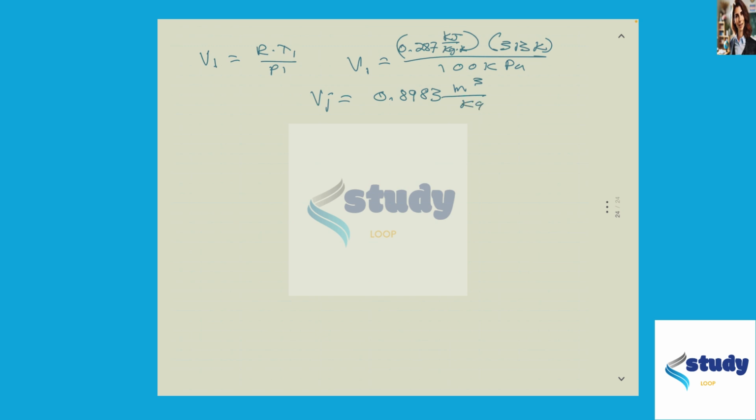And then we can find our mass flow rate. M will equal V-dot 1 over v1, and that will equal 14.167 meters cubed per second divided by 0.8983 meters cubed per kilogram.